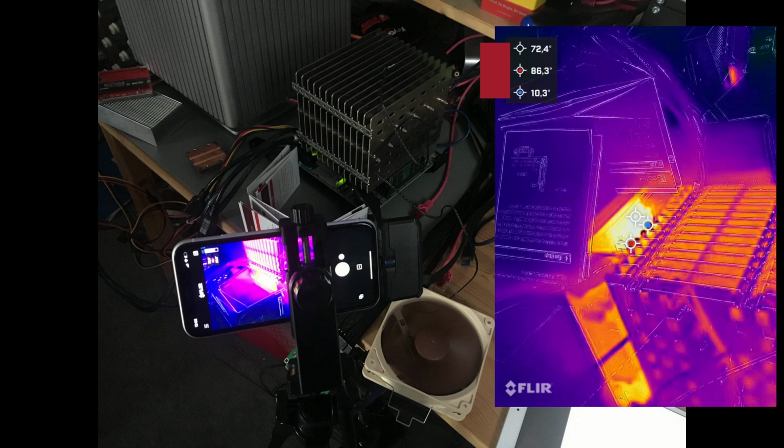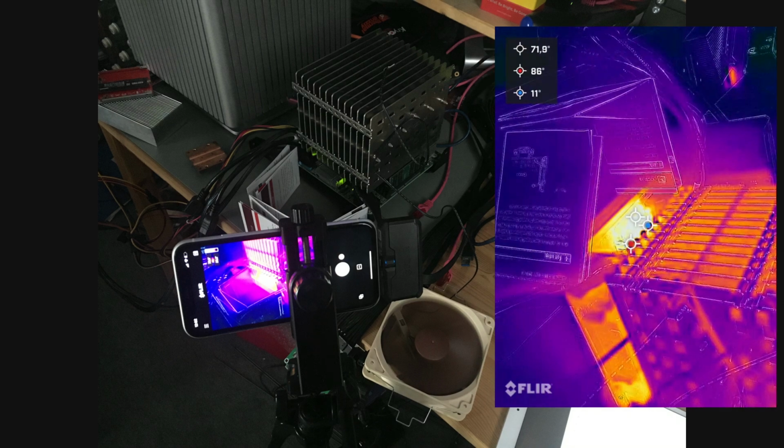We are sitting in a room where we have an environment temperature of like 23.5 degrees, so it cannot be that there on the system we have temperatures colder than that. So this clearly shows limitations that we have when measuring temperatures with infrared. It is a larger subject, but when measuring with infrared, the temperatures measured do not only depend on the temperature of the object under observation, but also it depends on the surface of that object.